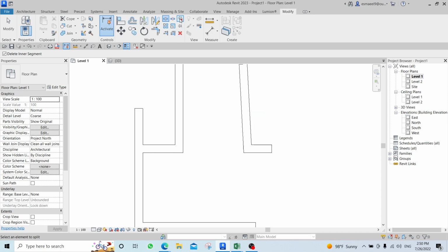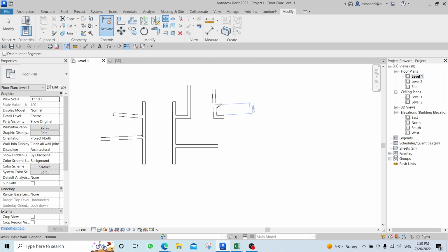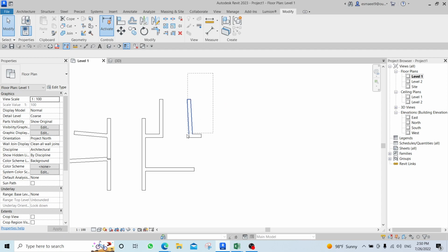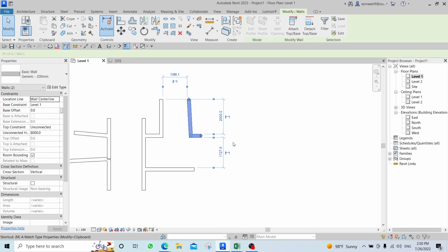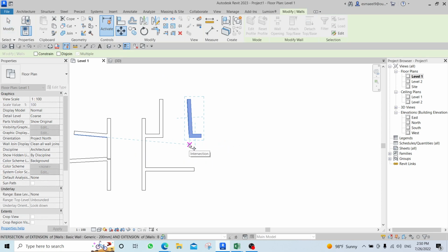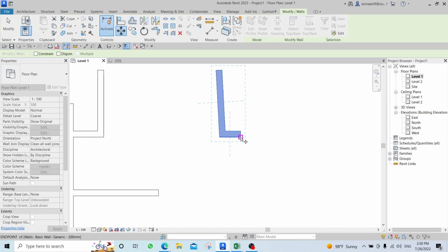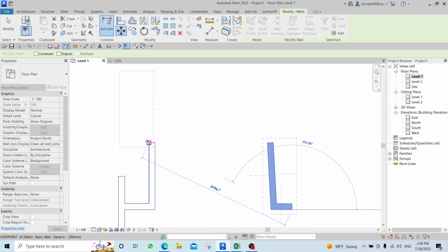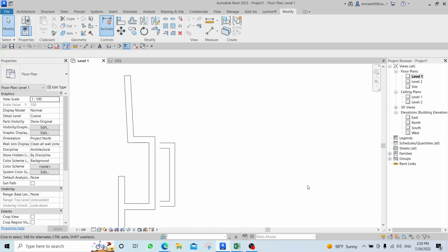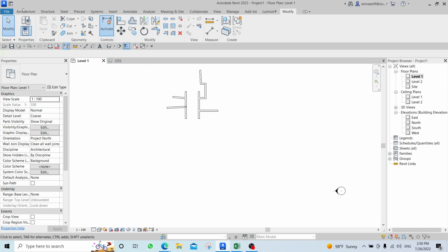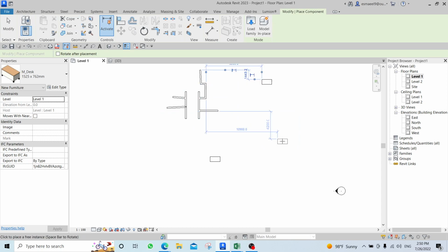I will go back to this bin and bin, moving into move, simply by selecting something, MV for move, click a point and then click the other point. MV, click a point and then click the other one. I will go back and bring an office or a desk, click it.